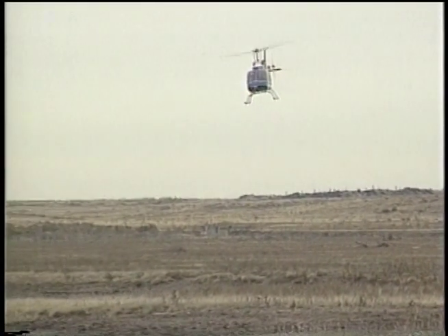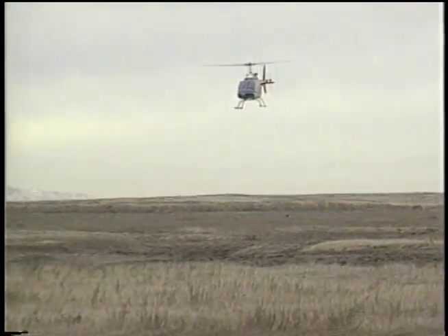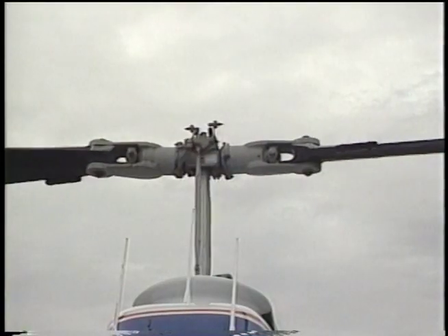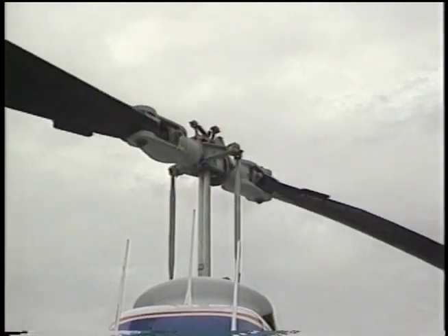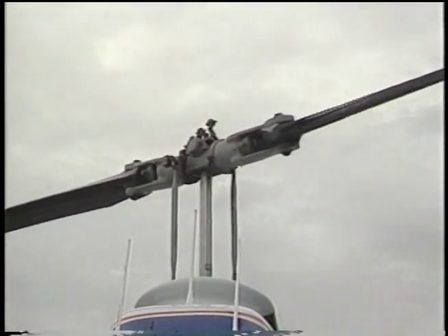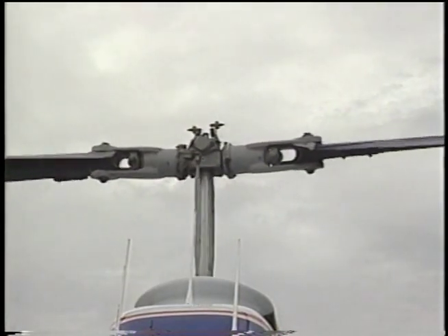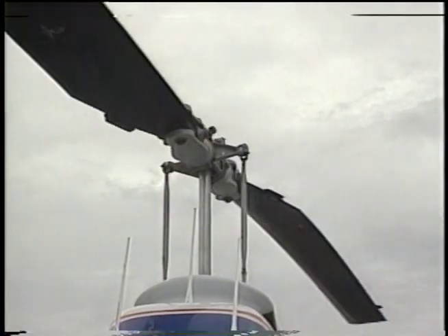During powered flight, air flows through the rotor system from the top and out the bottom. Helicopters have a free wheeling unit which automatically allows the main rotor to rotate freely if the engine fails or there is some other mechanical emergency. The rotor system then maintains flight RPM by reversed airflow.